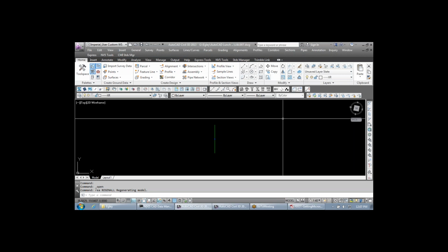And so you can have some issues where it's not actually calculating a 2-to-1 slope. It actually comes out 1.8 to 1. And then also with pipe network parts, verify dimensions and stationing of centerline. Make sure that the software is returning the values that you expect and anticipate.